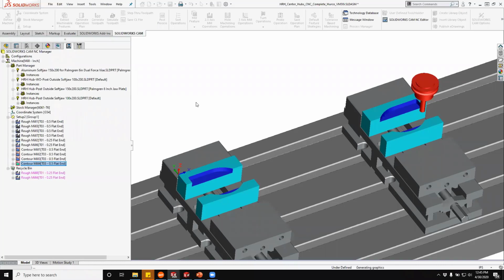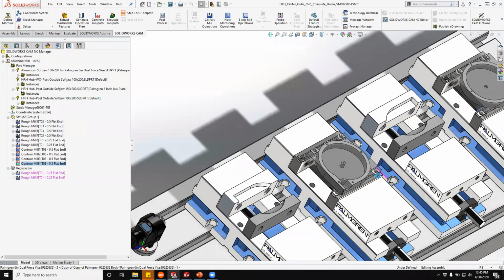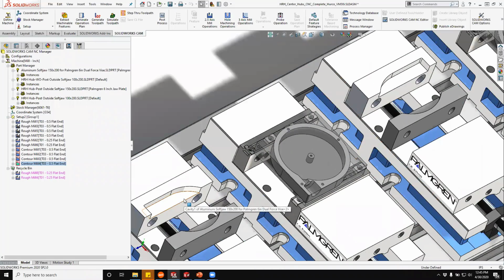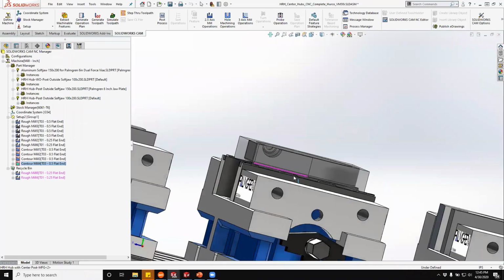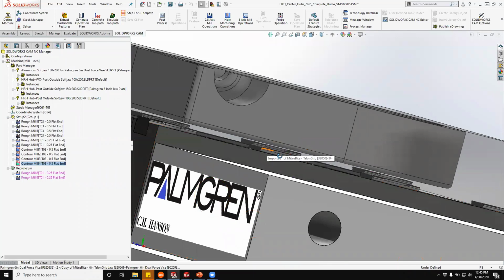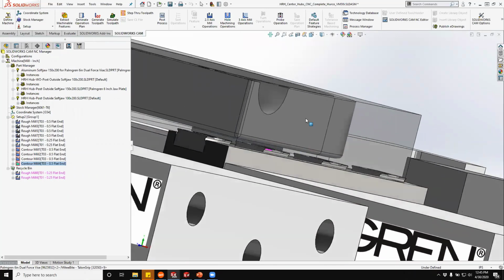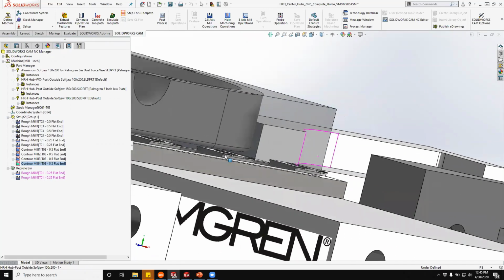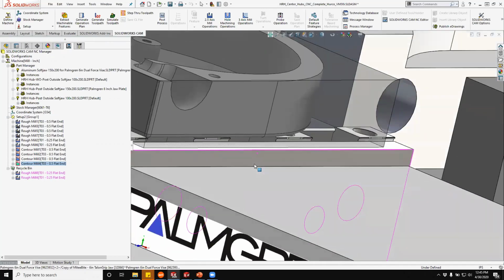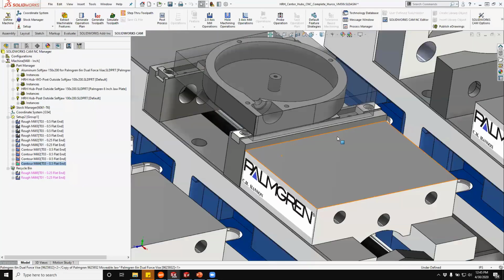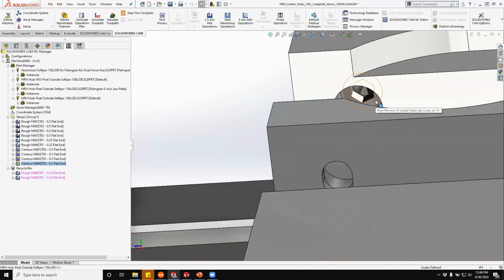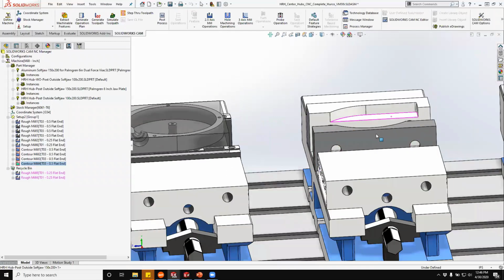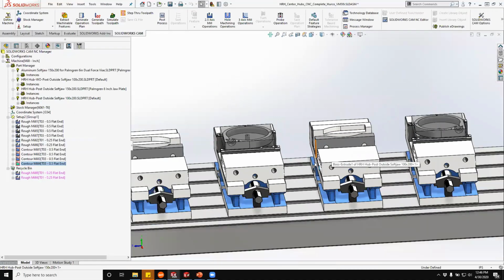When we jump into the SolidWorks CAM Professional, we get the ability to go into the assembly mode, and the benefits of that are that you're in the ecosystem, first of all. We can use that assembly to generate things like soft jaws. We can look for interference. It's nice to know how high our Mighty Bite clamps are going to come up and how much space we have as we cut down before we might have an interference condition with that Mighty Bite clamp. We can also look at when we're drilling, is there a possibility that we're going to hit our bolts in our soft jaws? And so that all becomes very nice.